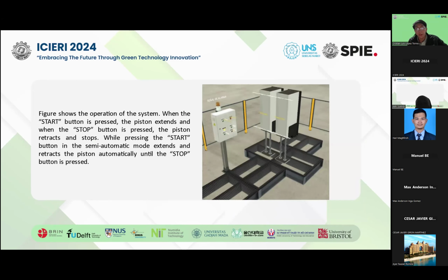For the simulation in Factory IO, to ensure the effectiveness of our design, we created virtual simulations in Factory IO. These simulate control panels, including four main control buttons, pilot lights, and dedicated emergency stop buttons. There are also two green buttons that let the operator select between manual and semi-automatic mode. These simulations allow us to observe how the machine operates under both modes and test the control features before building and fixing the machine.